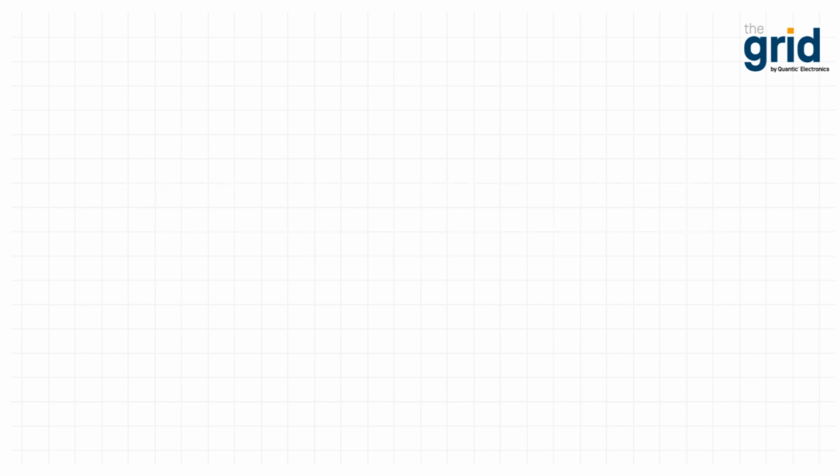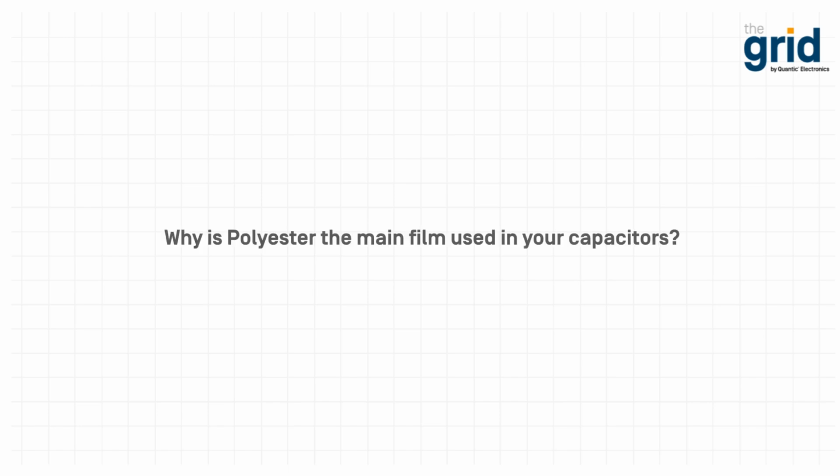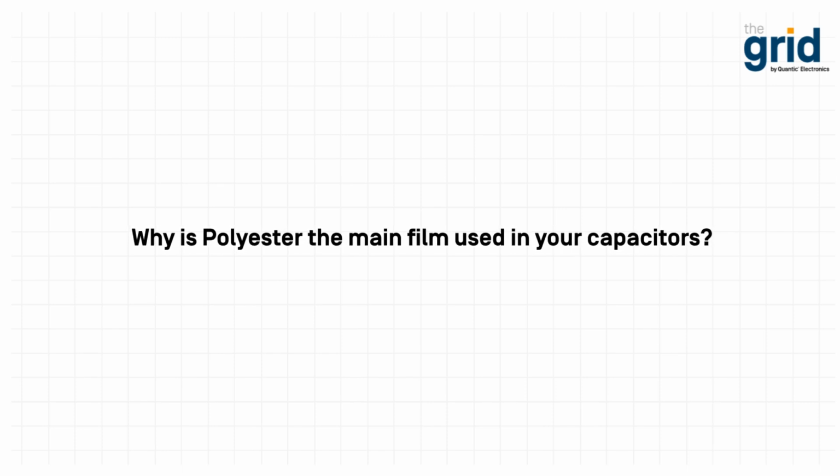Why is polyester the main film used in your capacitors? Okay, great question. If you're looking at the film capacitor market in general, you'll probably see a lot of polypropylene out there, especially for AC applications. Polypropylene is limited to 85 degrees C typically. Its melting point is of course much higher, but given its self-heating ripple current ratings, generally limited to 85 C. You'll see some exceptions that go up to 105 C. We use a special type of polyester material that can operate in AC environments up to 125 degrees C.